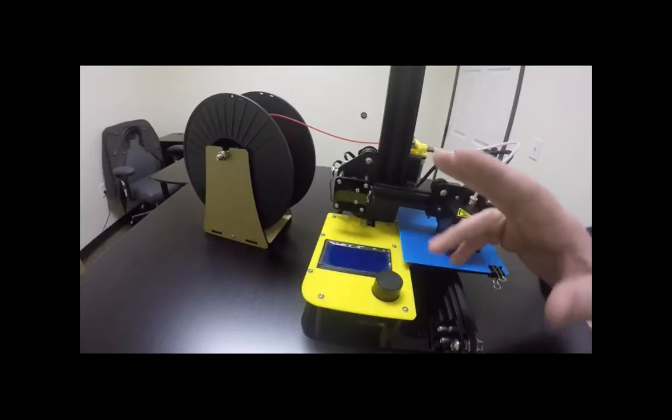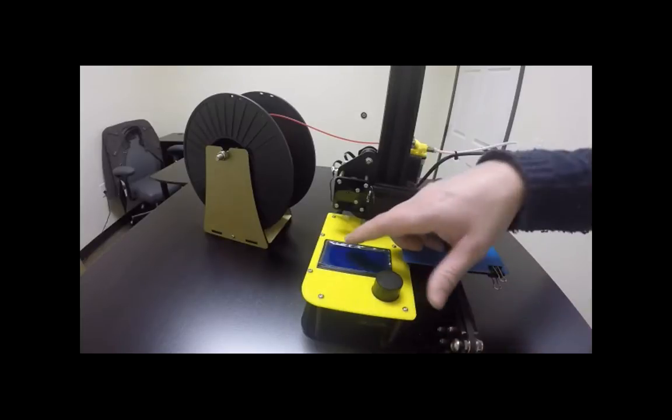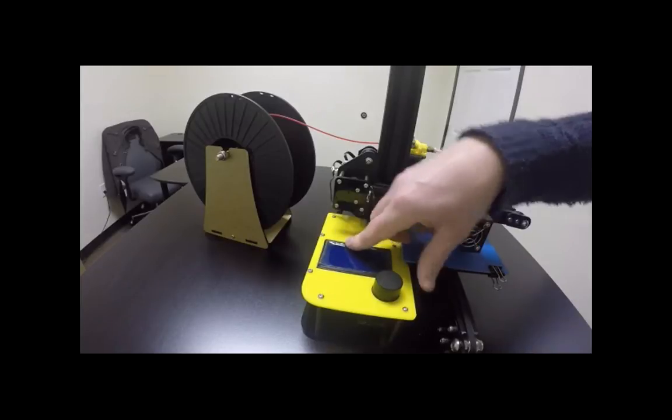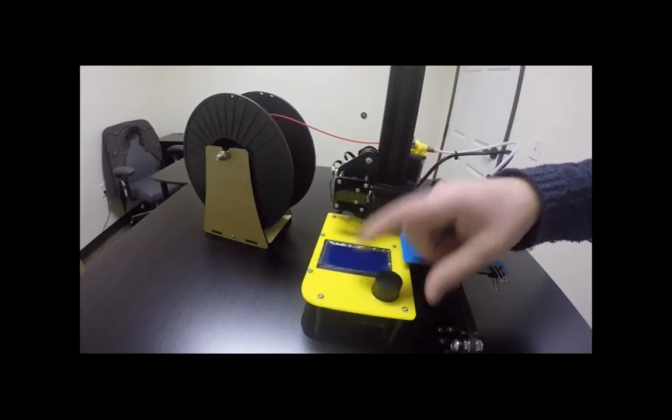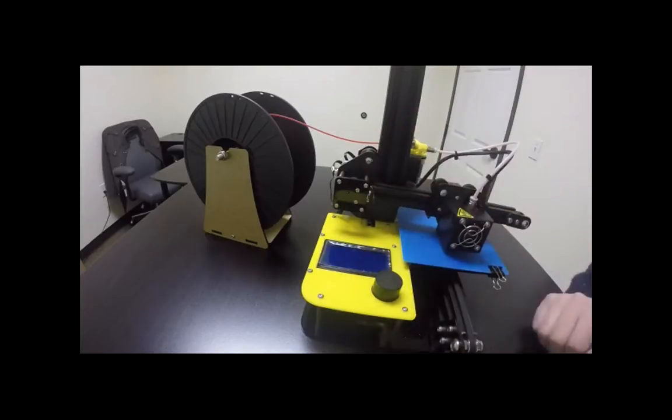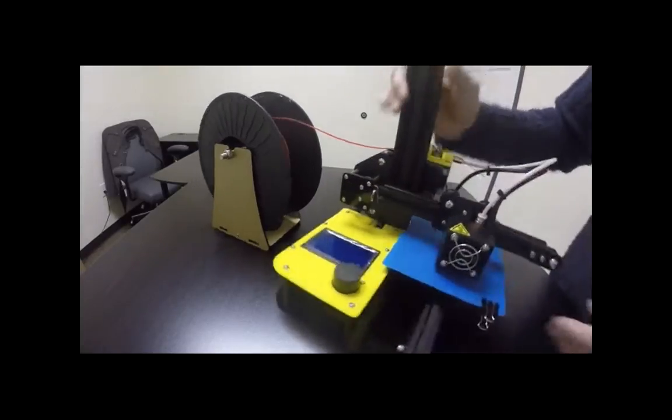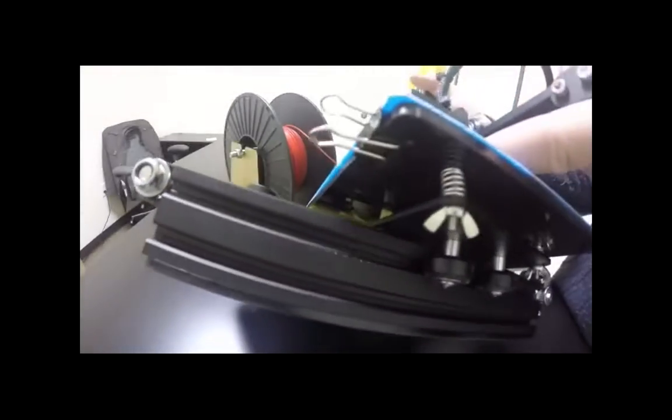All right. And then when you tap preheat PLA, it's going to heat up. You'll see the temperatures going up right here. So it's going to have 190 on the top, and then on the bottom is the temperature it's actually at. And that's in Celsius, and the only part of this that gets hot is the nozzle that's inside here.